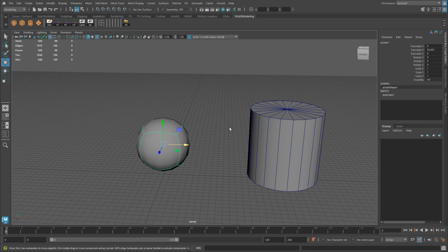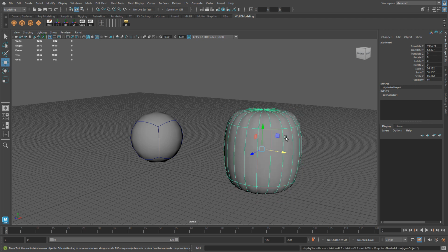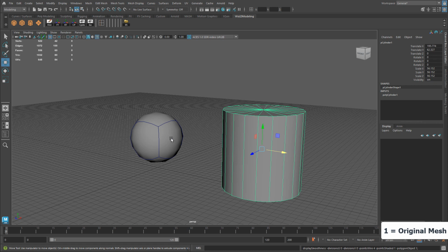Now my cube is a sphere. You work with a cylinder or anything else basically. Hitting a specific shortcut key, this will turn on subdivision mode preview or smooth mesh preview and collapses your object. So the shortcut key that most beginners press and they don't know how to get it back is 3. 3 is a shortcut key for subdivision preview mode. And in order to get back to your original object, you have to press 1 to reverse it and disable